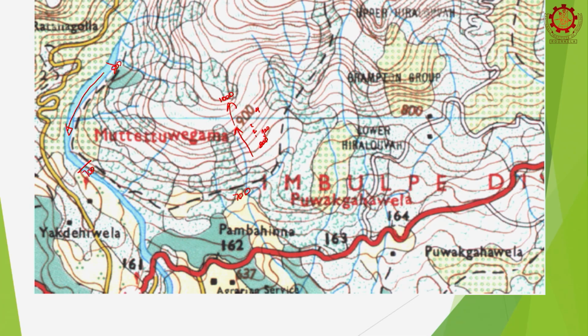So, between this point and this point, if you want, we can put up a hydropower plant with a 100 meter head, right. That is how we identify hydropower opportunities. But if you go further down, there is another line here which must be below 700 by 20 meters. Here is another line, this may be 680, this may be 660 and so on. I am just not putting the exact numbers, you can find out later, but I just put some tentative values.